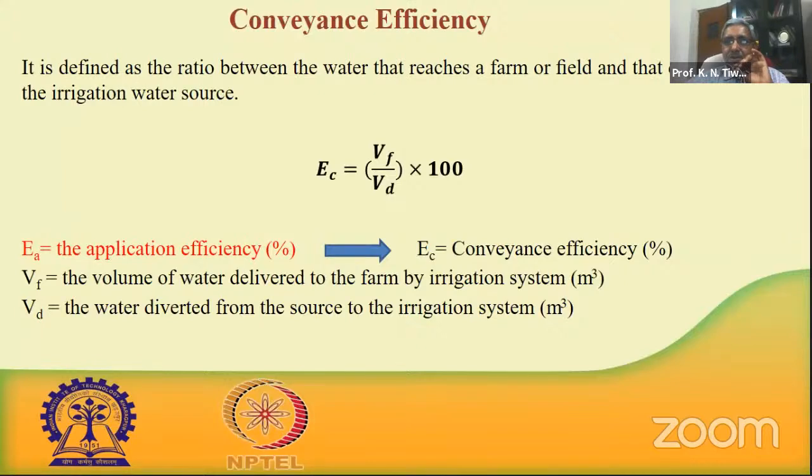There is the resistivity method, where the resistivity of the rock or the groundwater possibility is found out. But yes, some companies manufacture devices and use a term called soil water diviner, which is similar to the time domain reflectometry or frequency domain reflectometry, which I have discussed in the class. That device is used for soil water content or vadose zone soil moisture content. It is not used for finding out the groundwater.